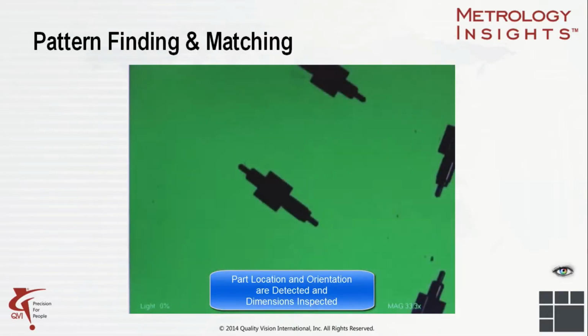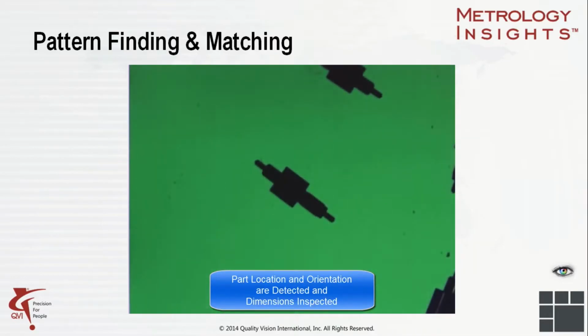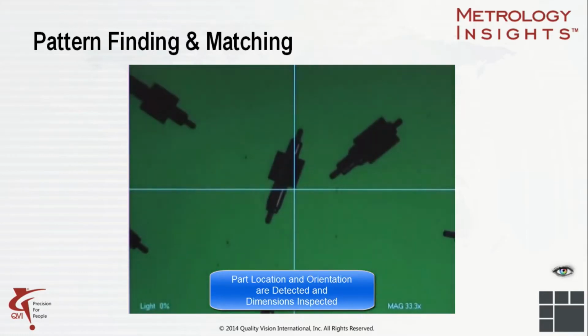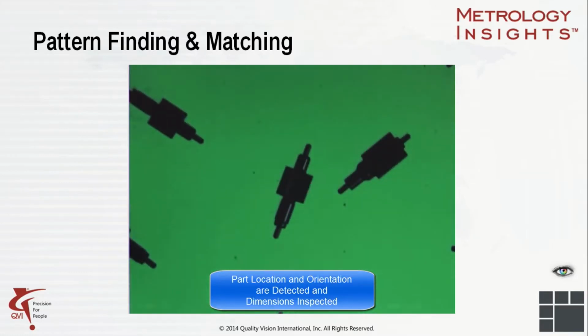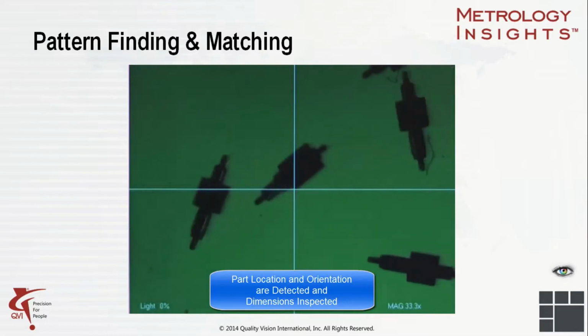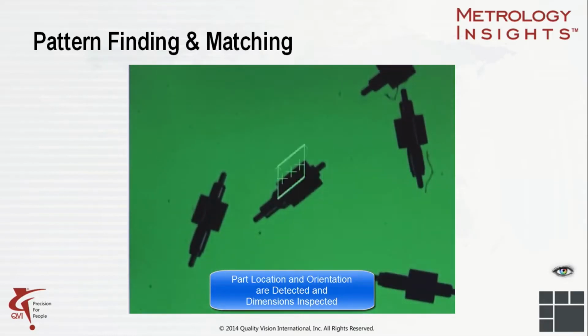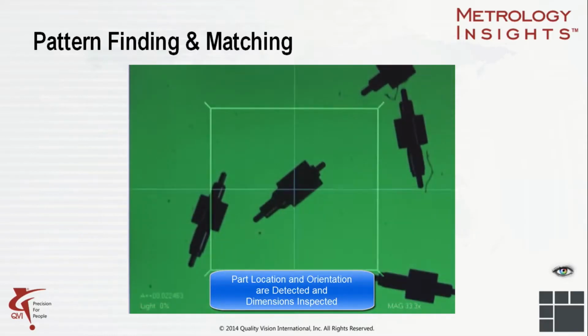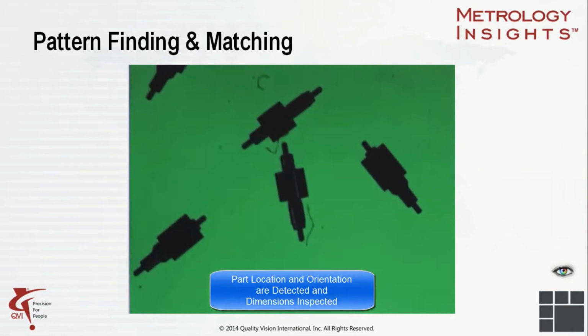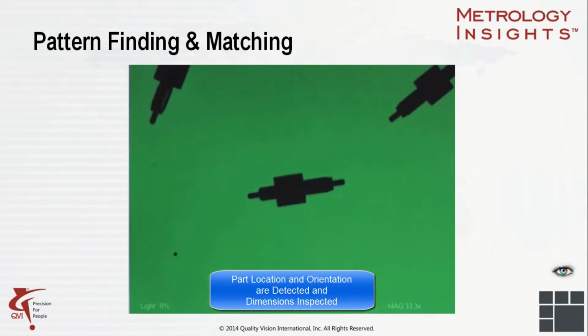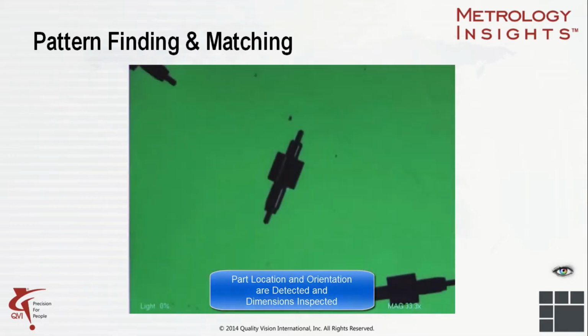Here, we place a random batch of parts on the measuring surface and use a routine to map the entire measuring range. We then form a big picture of the stitched fields and identify where the parts are, what orientation they are in, and then we are able to apply the detailed measurement routine, using video or multiple sensors such as laser or touch probe to complete the detailed measurements.